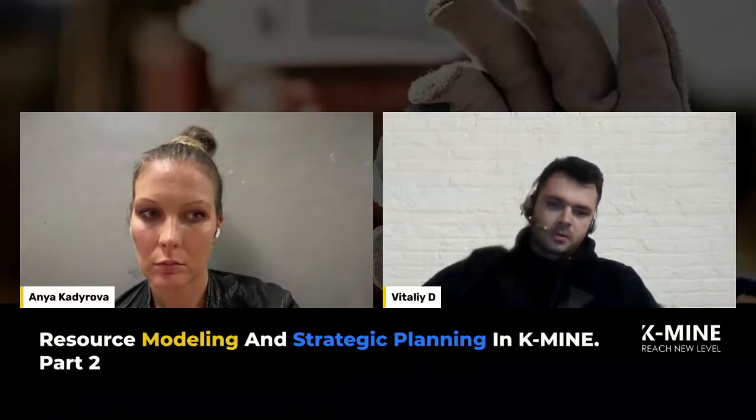Because we all know that the bigger the pushback, the longer, the more time we will need to obtain the ore, because there will be a lot of stripping. And if we have a narrow pushback width, it means that our productivity will not be reached. The next one is smoothness. It's about when we would like to connect the previous pushback to the next one. And of course, we will not create corners between them, like 90 degrees, because it will be unmineable at all and it will be unstable. So the connection between pushbacks should be smooth.